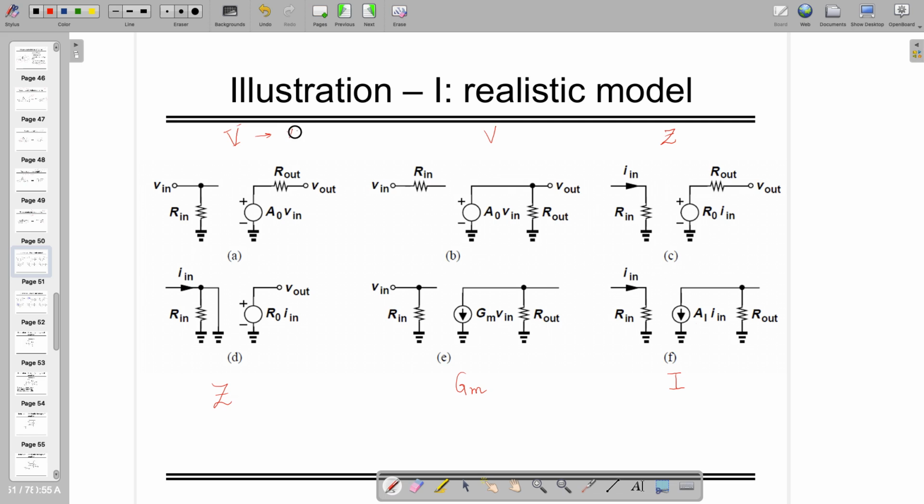or the voltage controlled voltage source whose input impedance we are expecting as infinity and output impedance as 0. By the way, this is what we want in the ideal case. So there, you can see infinite impedance is already there, but if I'm keeping something in shunt with that one, then this quantity will become reduced, or it will become realistic.